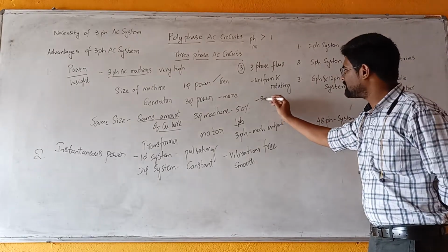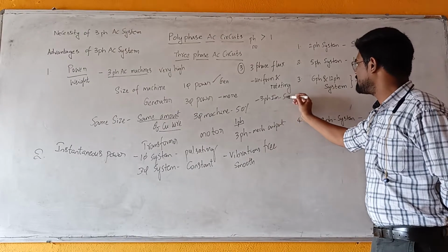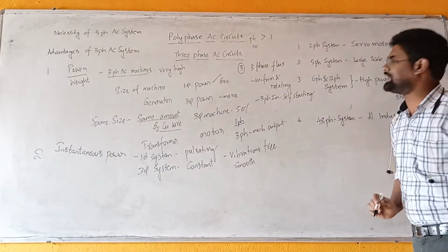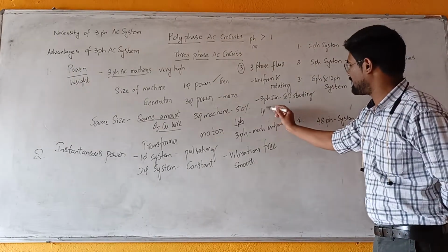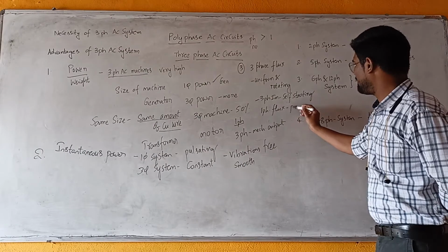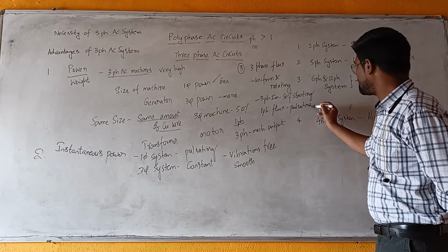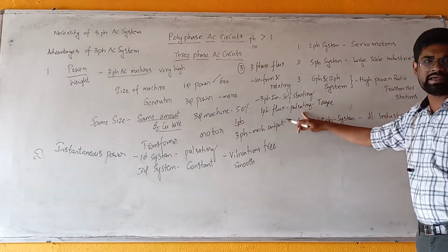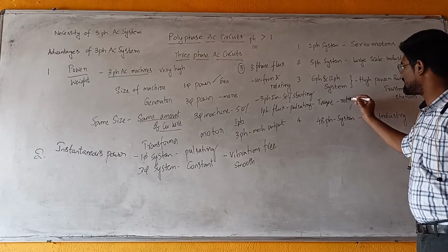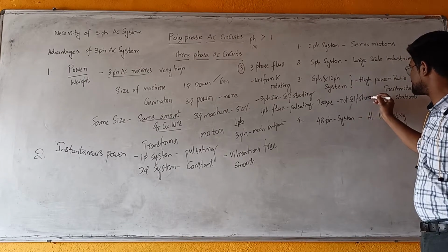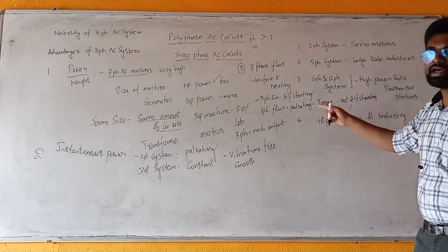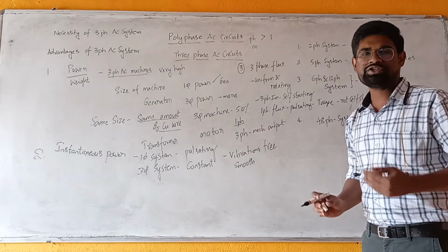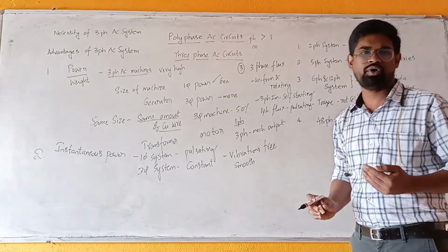Because of this, three-phase induction motors are self-starting, whereas in single-phase the flux is pulsating, changing. Because of this, the torque produced from single-phase flux is also pulsating, so single-phase induction motors are not self-starting motors. I am considering induction motors in particular because induction motors are the most widely used motors in the world.